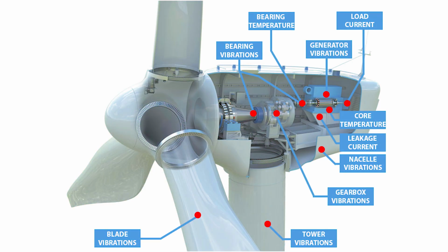Our solution for wind generators can wirelessly monitor leakage current and load current monitoring, temperature monitoring on bearings, gearboxes, generator core, insulation assessment, vibrations with FFT analysis.